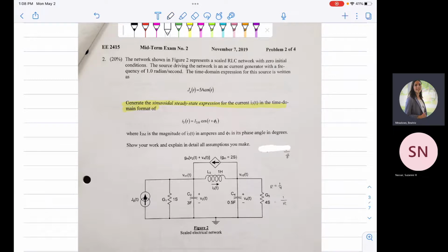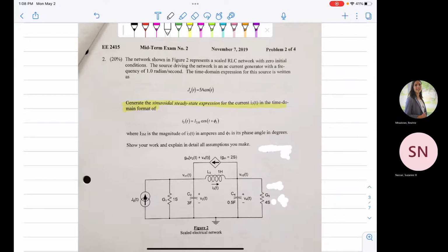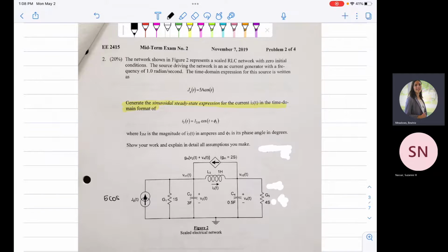We got both? Because I see current sources, and he also gives us G values. Nodal, exactly. There are no voltage sources. He's even labeling the nodes, and he gives you conductance. So it should give it away that you're going to be working with nodal analysis.